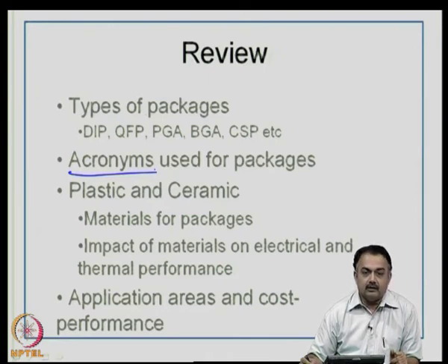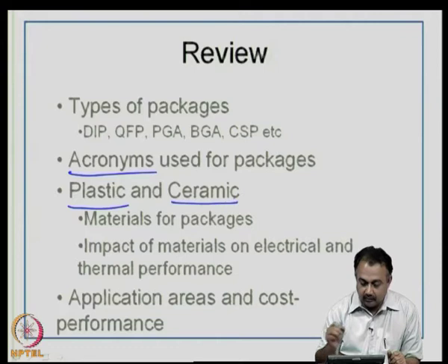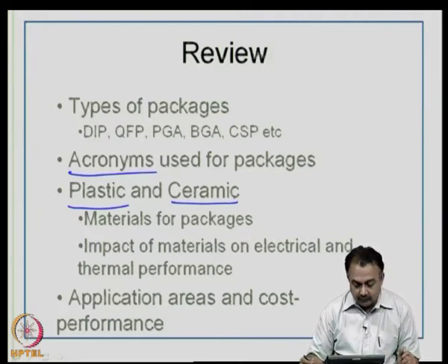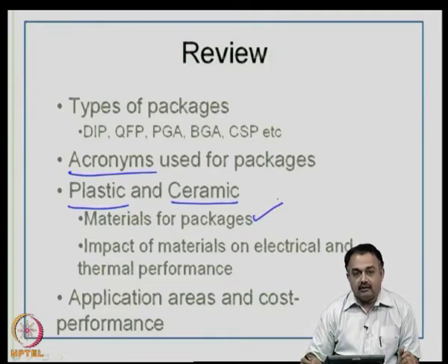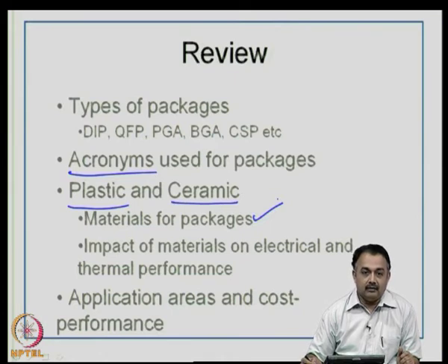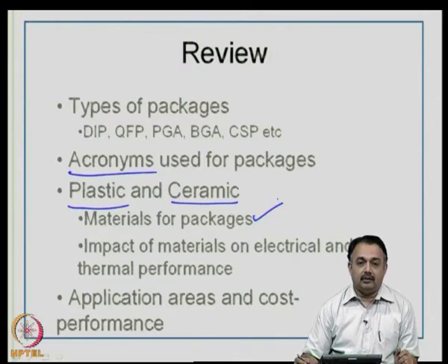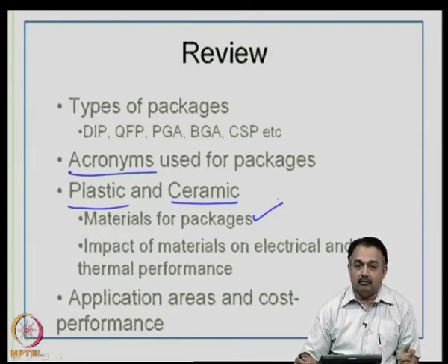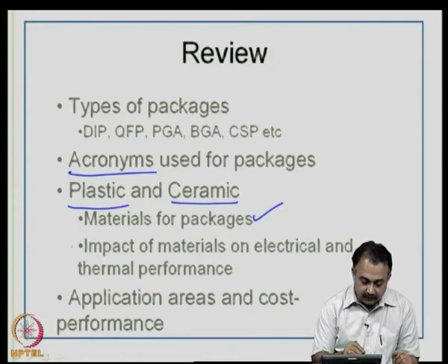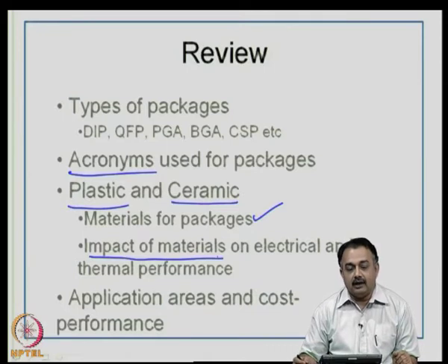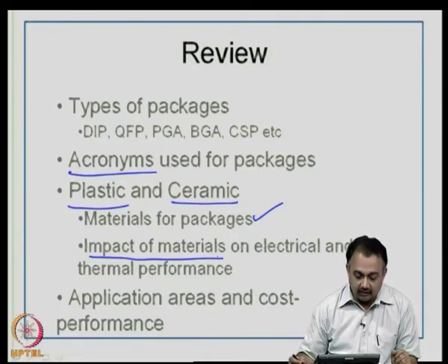We have also seen that basically there are two classifications from the material standpoint. Either it could be a plastic package or it could be a ceramic package. So, choice of materials is very important. A designer of a particular package needs to carefully look into the material properties that are being chosen for manufacturing a particular type of package, because as you know, these packages are produced in millions. Therefore, the accurate value in terms of electrical performance and thermal performance need to be studied at length, because you will appreciate that there is a large impact of these materials on electrical and thermal performance. We have seen a host of examples for this particular statement.